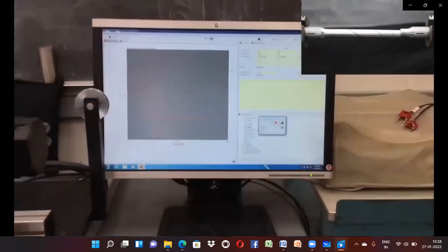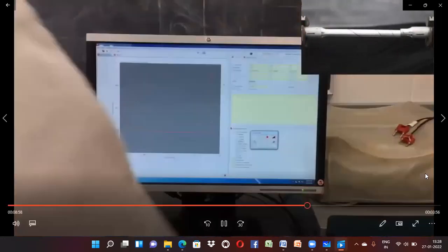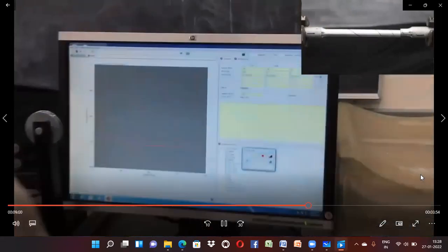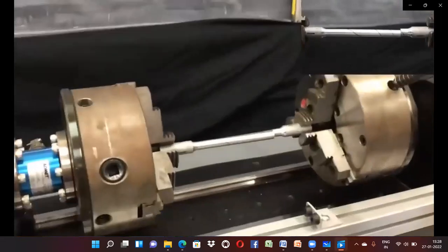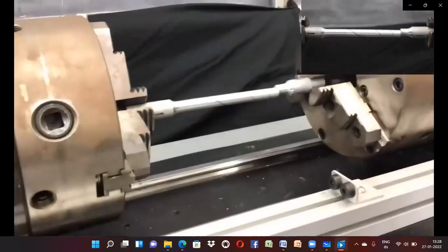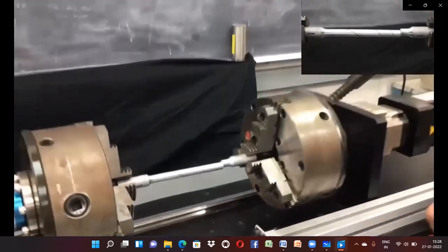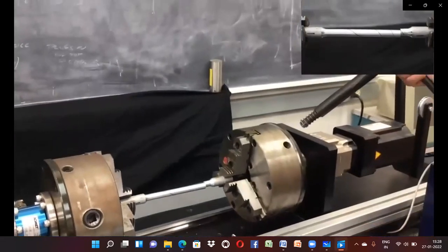And so, look at that. Sure enough, it fractured on the right end, and our load dropped to 0, which means this has failed. So they click stop. This doesn't stop automatically like the tensile and compression methods. This would just keep going until we stop it.